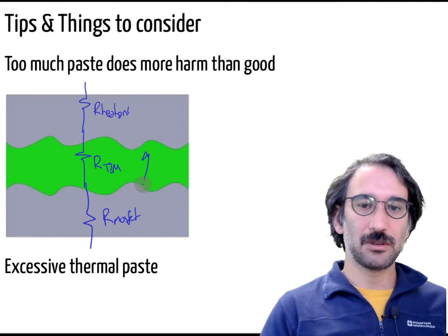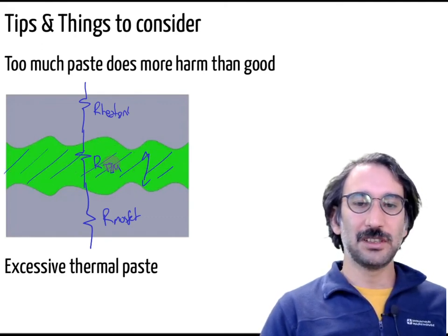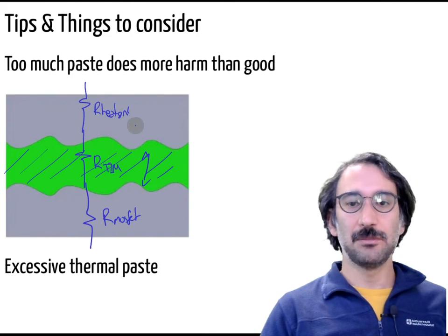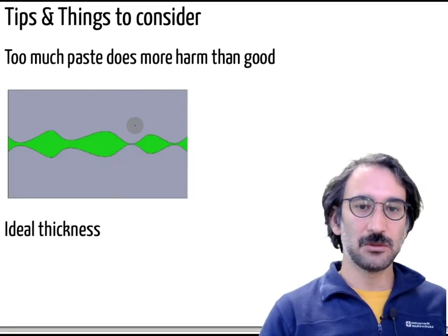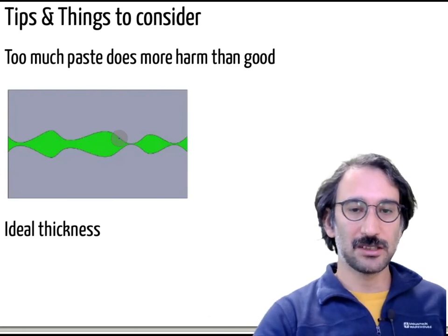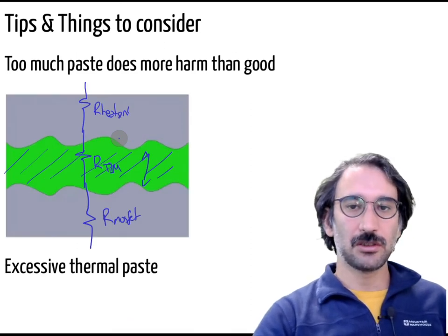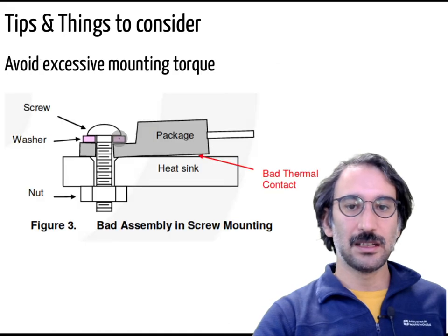You have, let's say, your MOSFET or your switch, and you have your heatsink, and in between you put a thermal interface material. Okay, so if you look at the numbers, that thermal interface is worse than the metal, but the idea is just to fill those gaps so you will have the maximum contact area for a better conduction rate. So just put enough to cover the non-idealities in the surface.